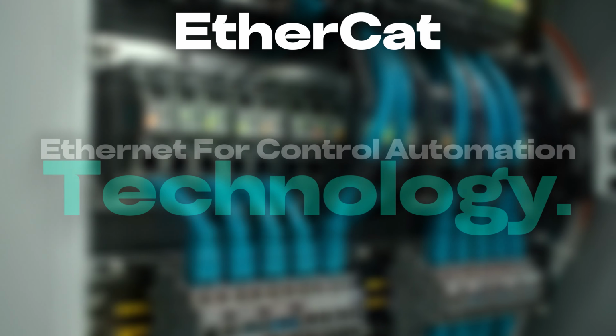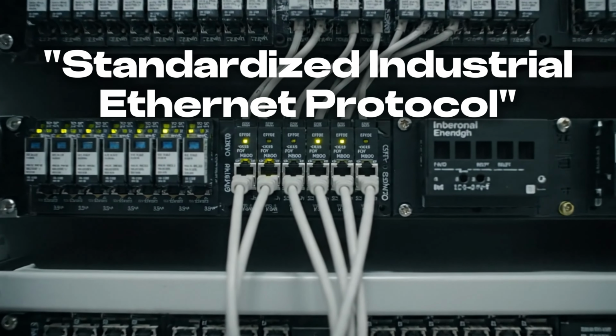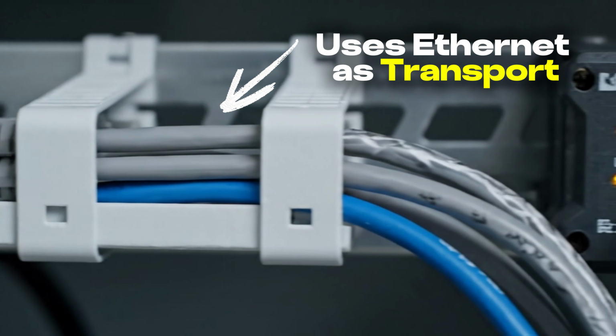EtherCAT stands for Ethernet for Control Automation Technology. It's a standardized industrial Ethernet protocol designed for instant data processing and automation systems. Although it uses Ethernet as its transport, EtherCAT changes the way data moves through the network so control systems can run with fast deterministic update cycles.